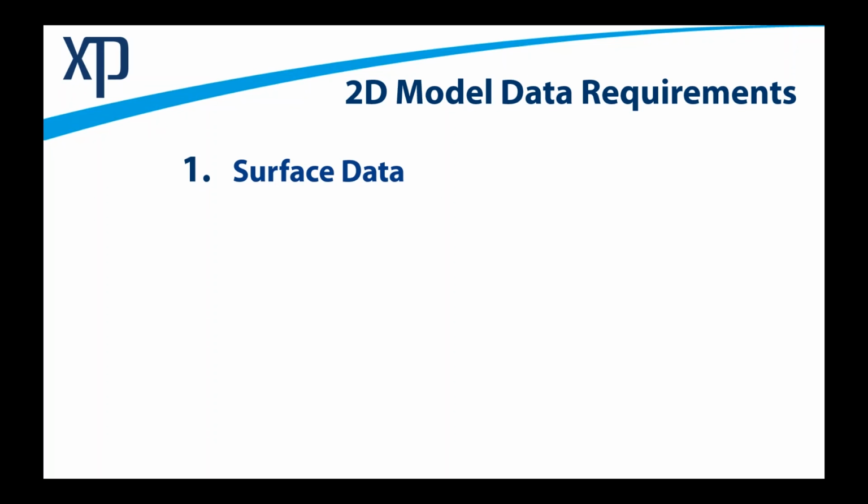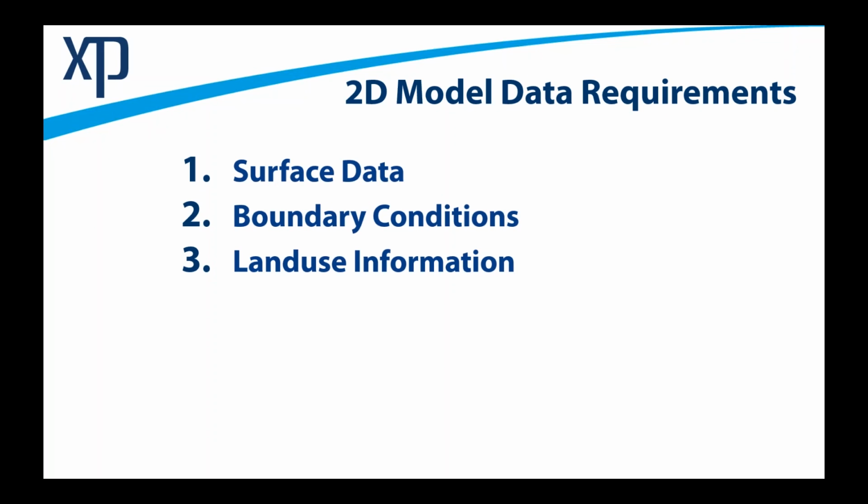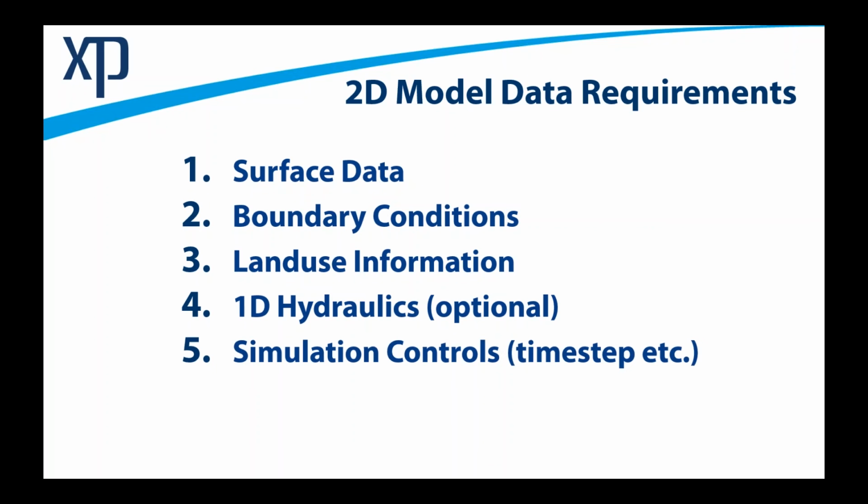Once you have all of those data sets, the final piece of the puzzle is really just setting your simulation controls within XP, and then pressing go, letting the model do its calculations, then just reviewing the results. So it's much less complex than what most people would believe. Four mandatory steps and then you're away. Yep. So that's probably why we're doing it these days, because the computer does the work. That's why it's easier than what people think than 1D modelling.